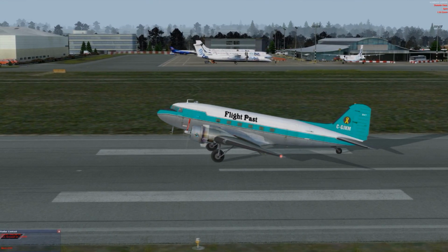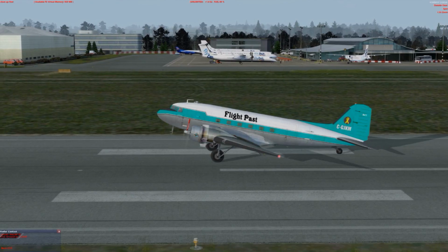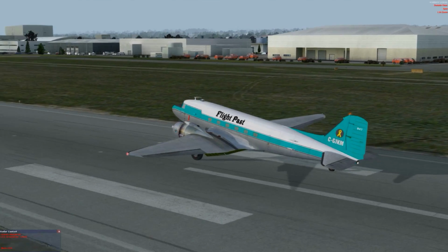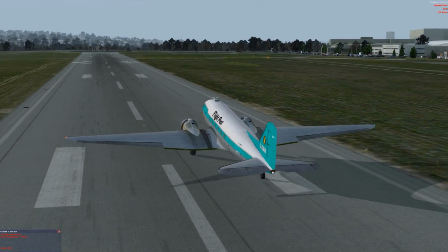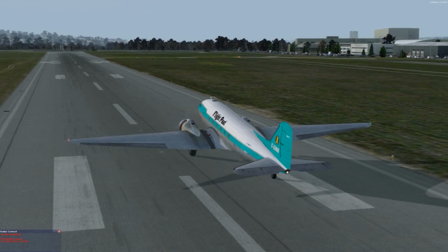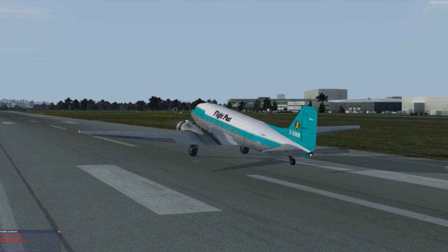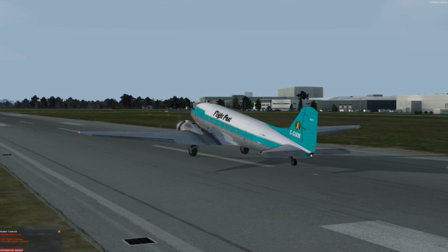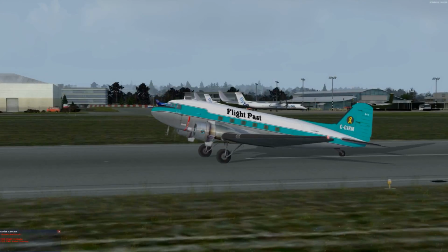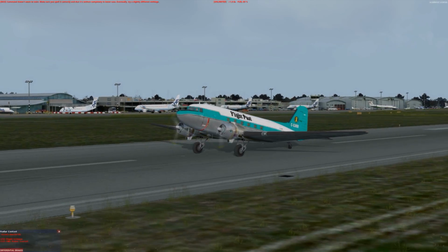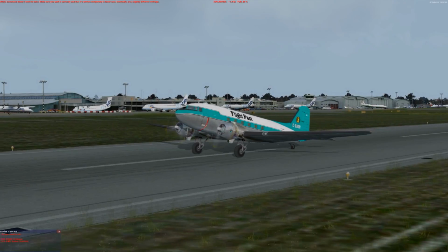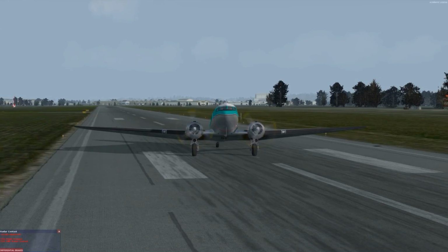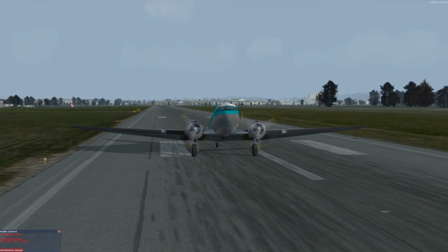Clean up flow. Ground, Douglas 231 at Delta 4. Flaps going up. Douglas 231, ground, taxi to the ramp. Taxi to the ramp, Douglas 231. Okay, after landing checklist. Cowl flaps full open. Flaps verified up. Pitot heat selected off. Taxi lights on as requested. Landing lights off on your command. Navigation lights turned off. David, unlock tail wheel, ready for after landing checklist.